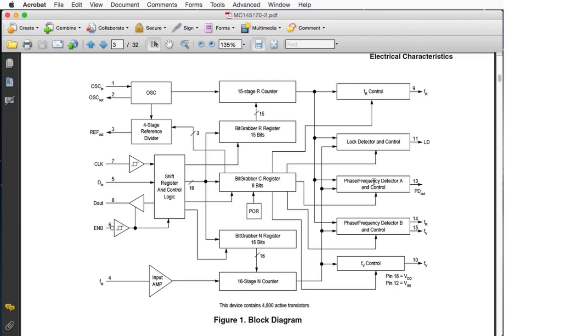That is then fed down to the phase detector section here, or phase comparator, whatever you want to call it. It could be 10 kHz or 5 kHz, depending on what step sizes are being used. Some radios use 10 kHz steps, such as the MB8719. The MC145106 generally uses 10 kHz steps, but it can be configured to do 5 kHz steps. There's a pin option on the outside for frequency select. But we'll go into that when I go into my simulator thing.